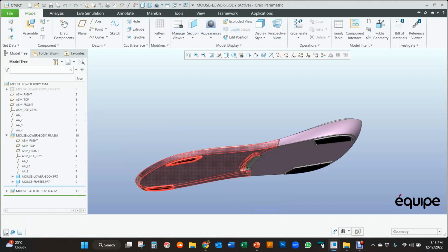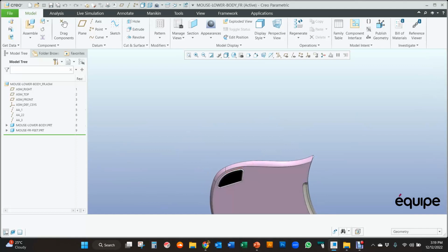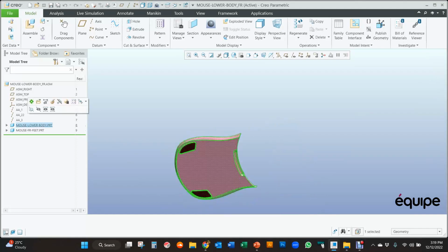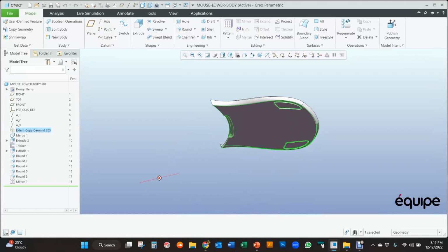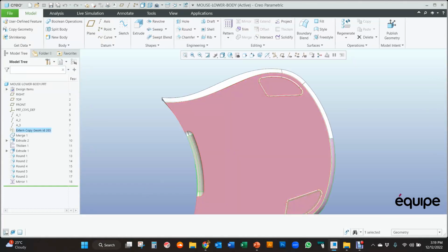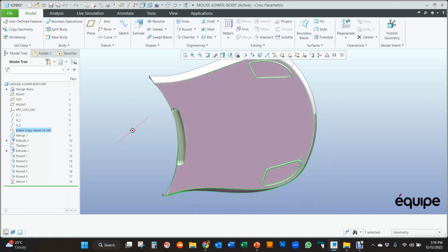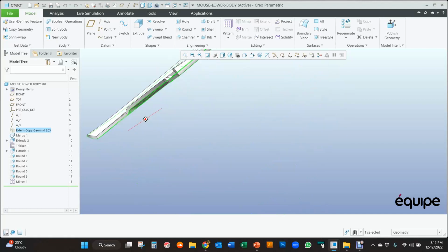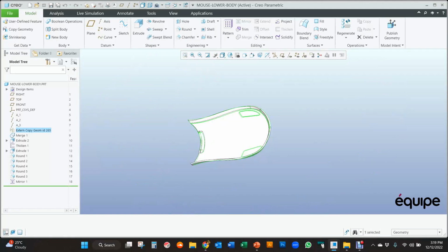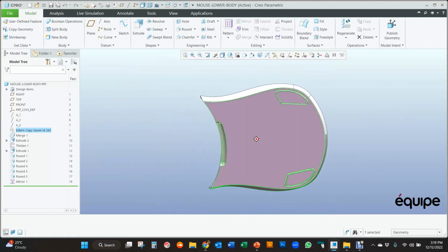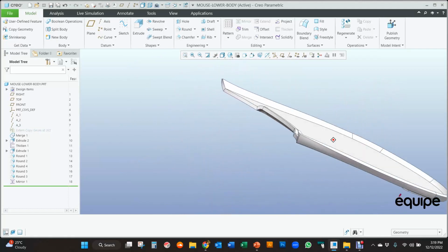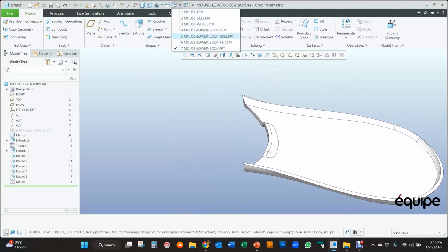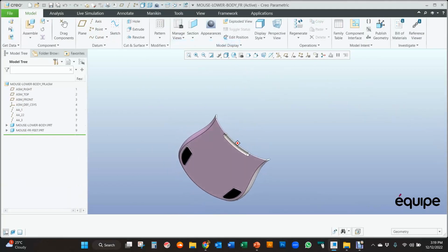Then if we come down into each sub-assembly, the lower housing here, we've got each of the parts which have an external copy geom brought in from that lower body skeleton, and then has the defining geometry to continue those features down into those subcomponents. So they're all where we want them to be, but they also align and correspond with the mating features on the mating parts.